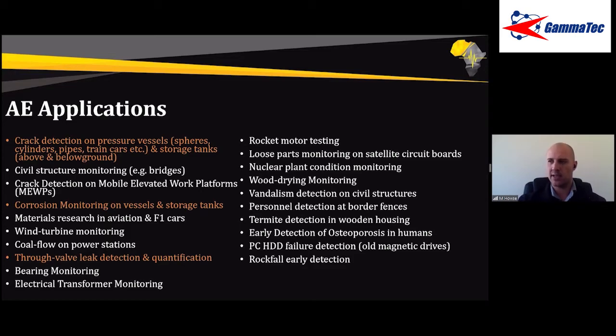If the sludge is too high, our sensors are moving further and further away from the floor. Therefore, we might attenuate out the signal, and there will be a cutoff to where we place the sensors, because we can't put the sensors directly at the sludge level. At the point that we may lose data and not detect it because it's attenuating out to the sludge, we will basically call off the test and say, no, let's rather not use acoustic emission for this. Rather take the tank out of service, desludge, or perhaps do sludge profiling to evaluate first, then desludge and go from there.